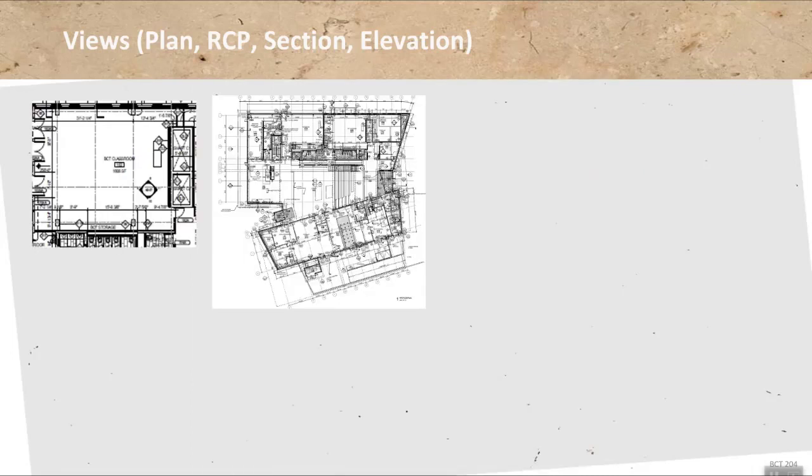Let's take a look at how this actually looks in our design building plan set. Okay, so this first one here is a floor plan. Again, we're cutting through the entire building at a 4 feet height of the finished floor. And then, of course, everything that's there is shown: walls, doors, ramps, etc. All kinds of things. So that's the floor plan. And then when you look at a space, our classroom here on the left, then you'll see what you're looking at. In this case, it's not a furniture plan, so you don't see the furniture.